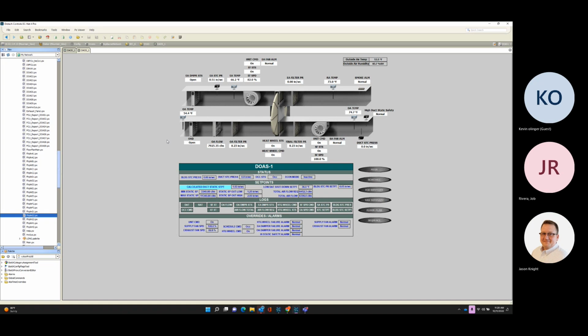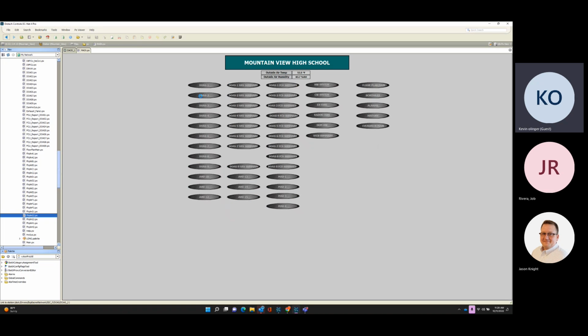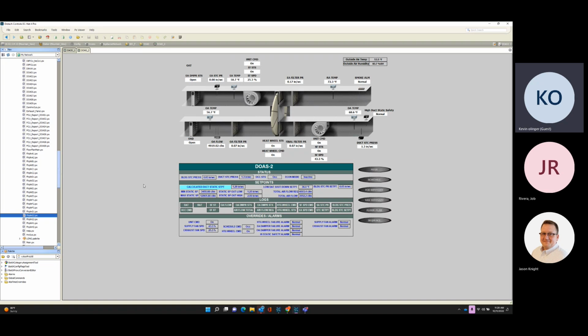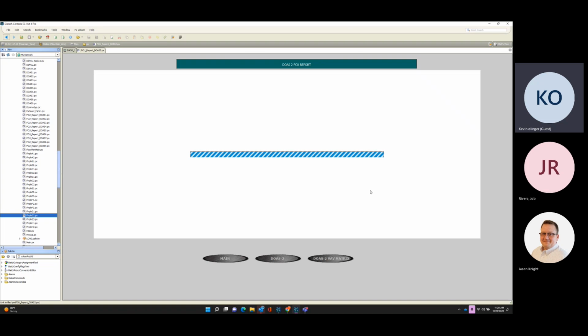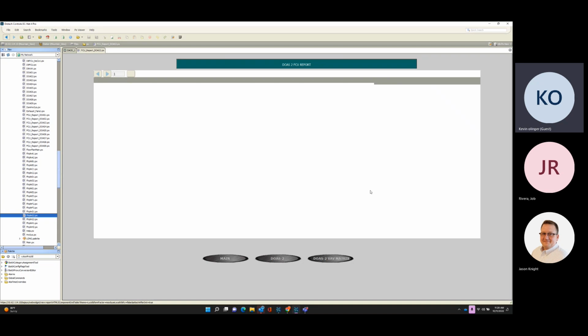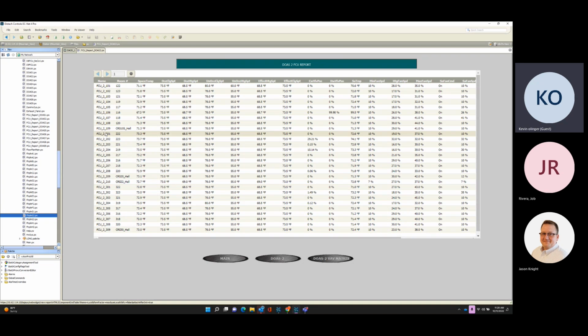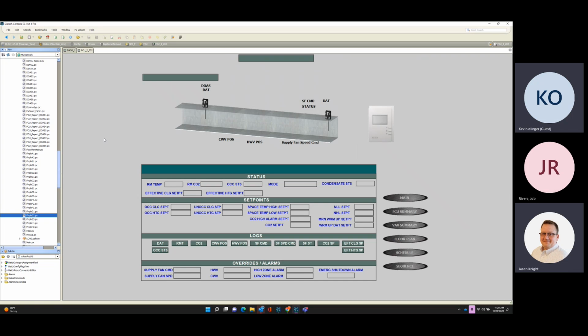And just to make sure that we're on the same page, the fan that you're talking about that backed way down, because you were saying the fan coil unit can be an ECM motor, a VFD driven motor, or a 3-speed. So those are the fans you're talking about that, when we're just in ventilation mode, where we're successfully maintaining temperature between set points. That is the fan coil unit fan that you're talking about that will ramp to the lowest level, not the VAV, correct? Correct. Okay, perfect. Thank you.